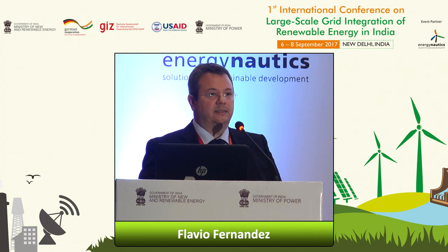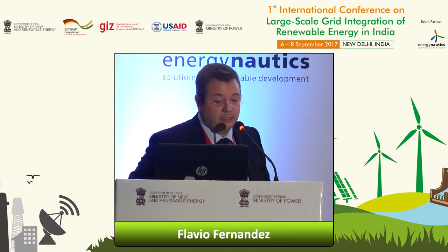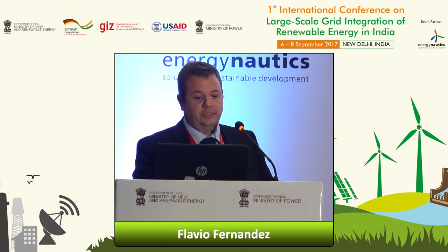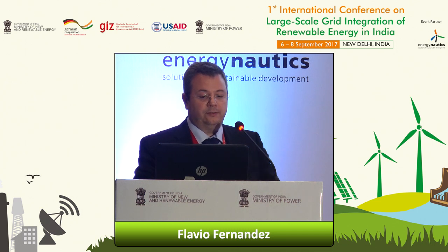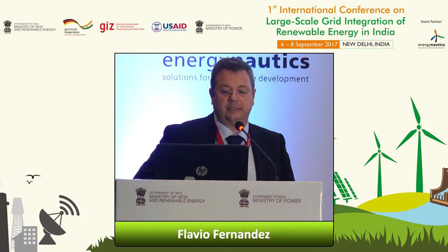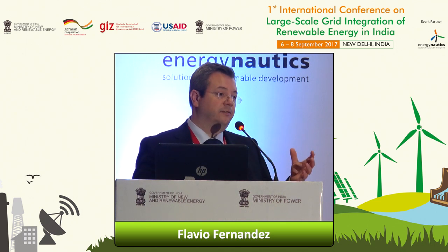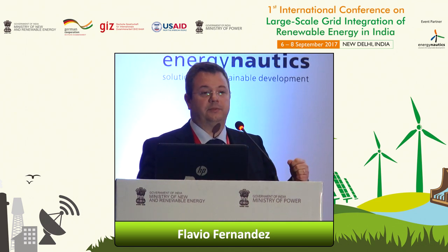this could be a doubly-fed induction generator. This is how the model looks at the top, and here at the bottom left you see the representation. You can see that for the PWM converters, you are actually using a representation of the converter bridge with the IGBTs.